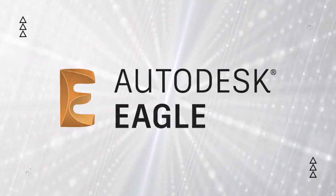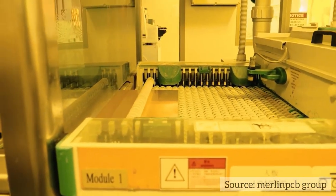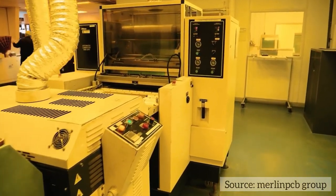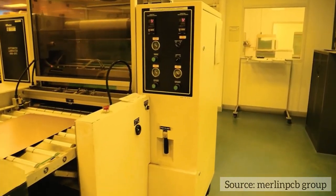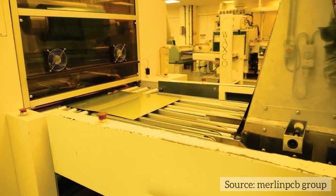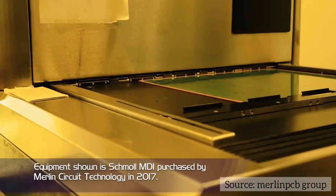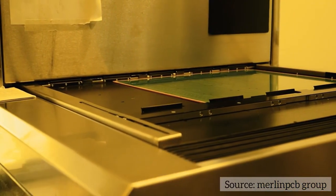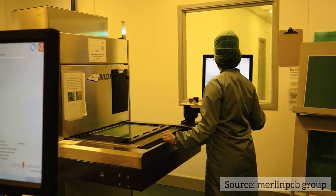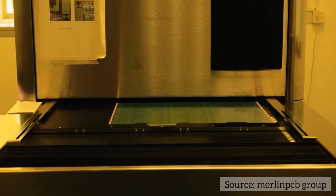After you understand how to make a PCB design using Eagle and also how to make 3D design using Fusion 360, in this video, we're going to learn more about Eagle manufacturing files. These files are used when we want to print out our PCB design. There are two types of manufacturing file we're going to learn: the Gerber file and the drill file. In this video, we will focus more on the Gerber file.